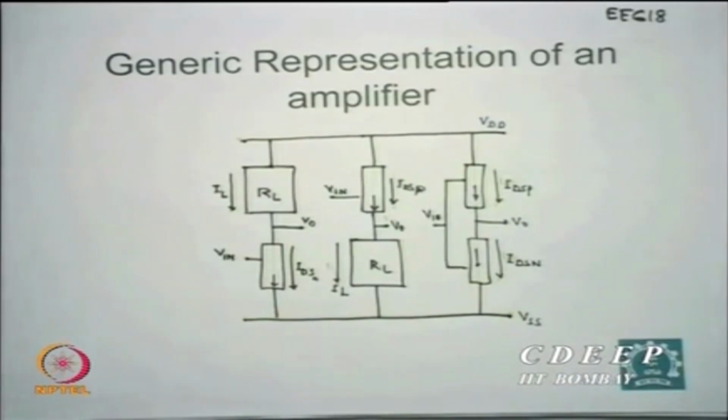Is that clear? Whether it is electrons or holes, though they do move opposite, the net electrical current external to that is always unidirectional from positive potential to ground or negative potential. That cannot be changed. This is Kirchhoff's law and nothing much can be done about it. So this is a p channel device, same technique.